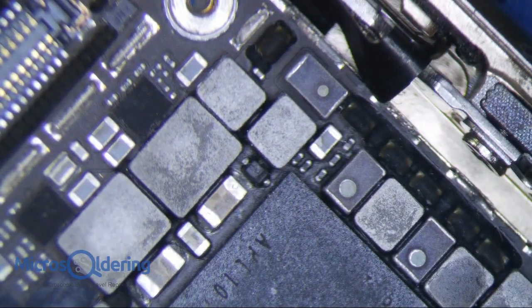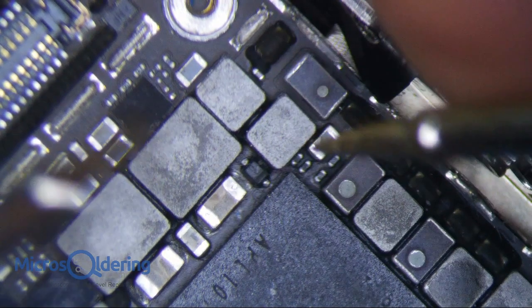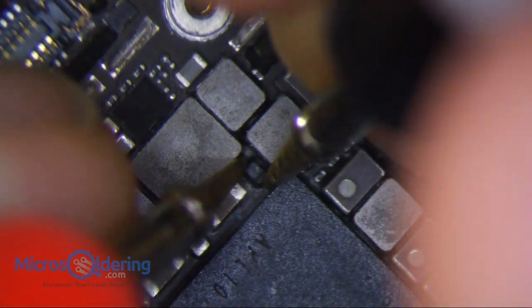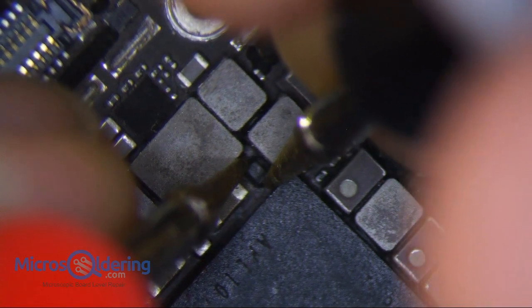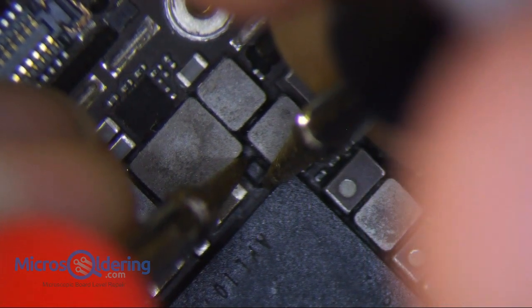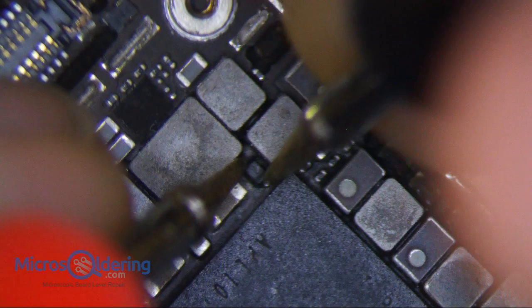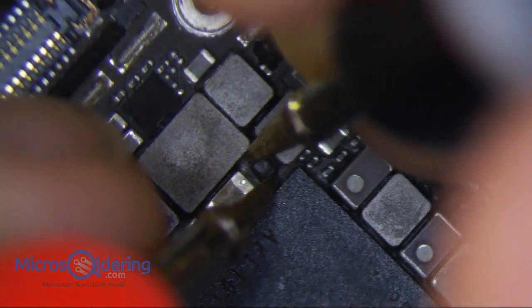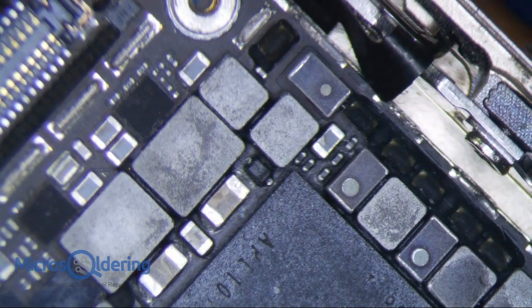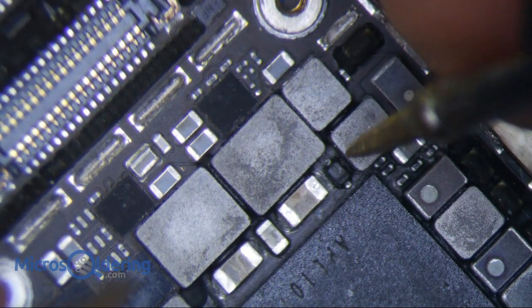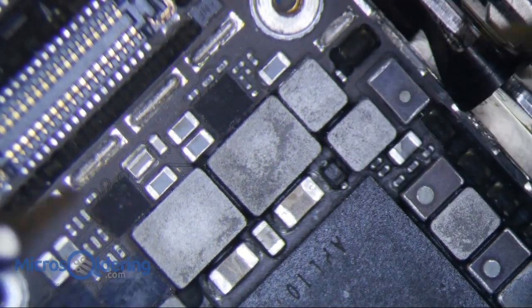In order to test a diode, you just put your multimeter into diode mode and measure across both sides. This is when the positive and negative actually matters. So you should get roughly 0.2 volts on one side, and OL going across the other, which is what I'm getting. So from there I know that this diode is fine, so I'm not going to have to replace that diode.